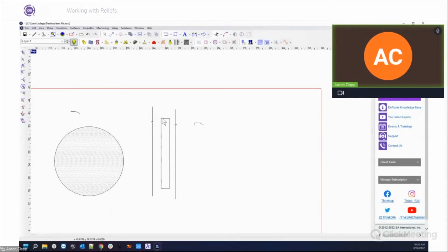What I'm going to do is start out with this rectangle here, and I'm going to start with my rails. I just drew these rails. They're exactly the same length, and I'm going to attach them to the sides of this object. So when the object gets swept through, it's going to sweep it right down the middle. That's kind of what the sweep to rails does.